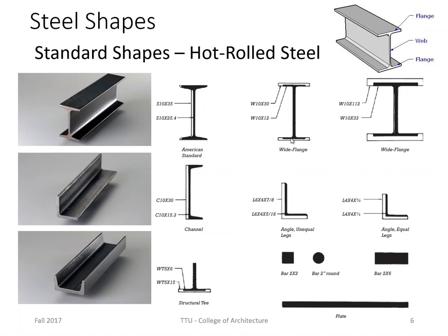And of course, the more steel that's in the beam, the stronger it's going to be. In a wide flange beam, you can see that the flange is wider, as you can see right here. And it has a whole range of different weights, which just add more steel, even though the depth is the same. This is a W10 at 33 up to 112. And what that means is the weight per linear foot of the beam.